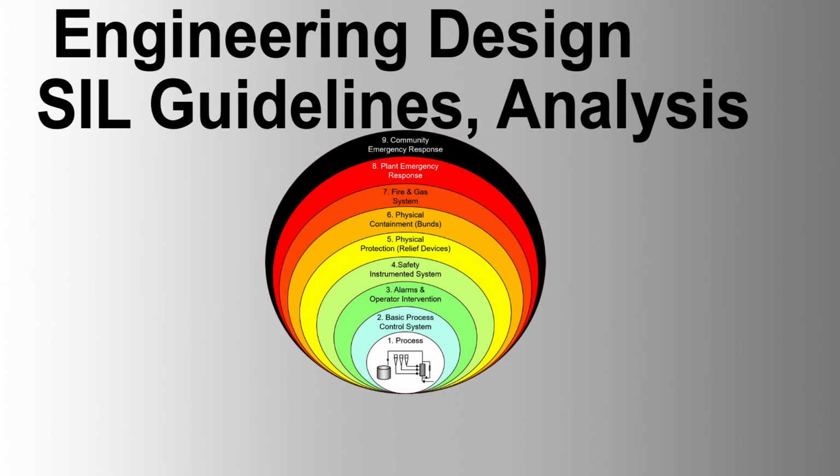In practice, the choice between Markov analysis and FTA will depend on the specific requirements of the SIS evaluation, including the complexity of the system, the availability of data, and the need to account for dynamic factors. Often, a combination of both methods can provide a more comprehensive assessment, leveraging the strengths of each approach.